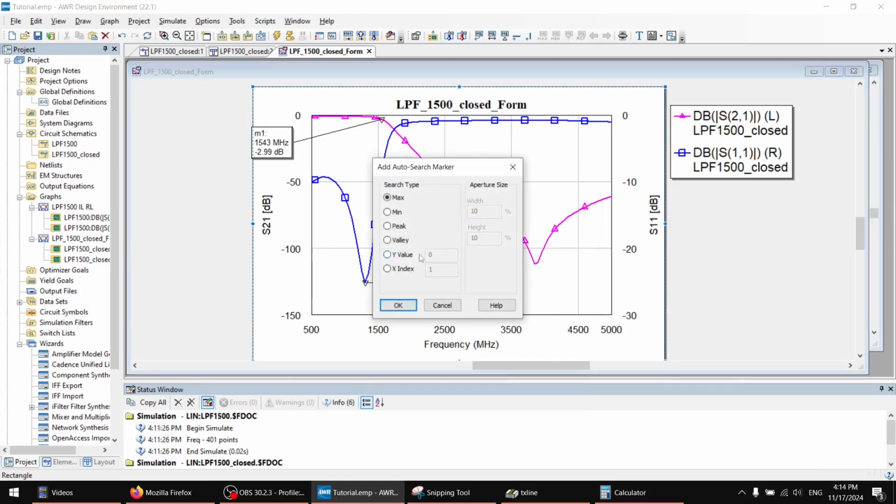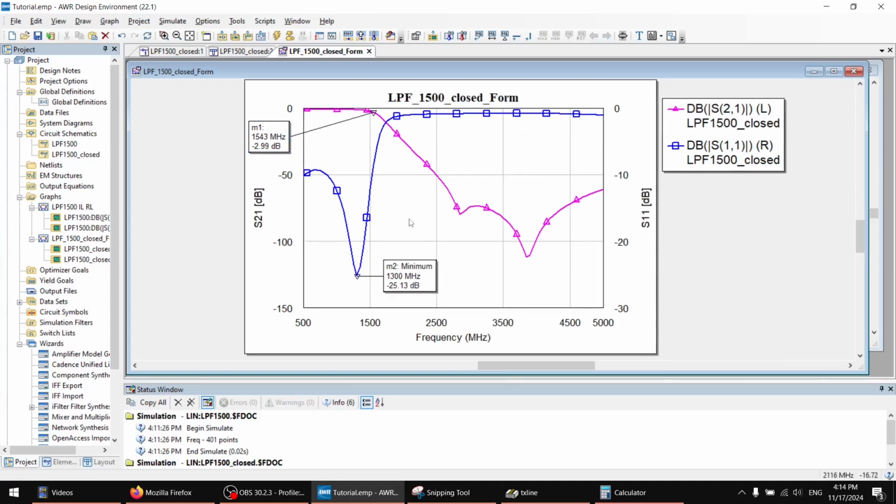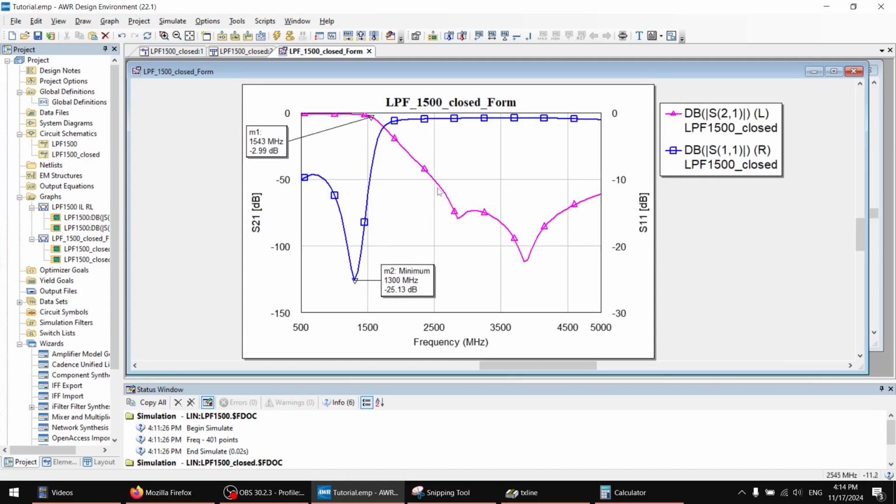And you can also use this for specific values. So you can see how that works. Very, very handy. Of course, you can also change the axis in the previous options, but this is, I think, quite nice, quite better plot than we have seen previously. You can see the 50 dB, so quite strong attenuation is about at 2.5 gigahertz, and the losses in the passband are about -1 to 1.5 dB, I would say. So not the worst filter, but this is a closed form.